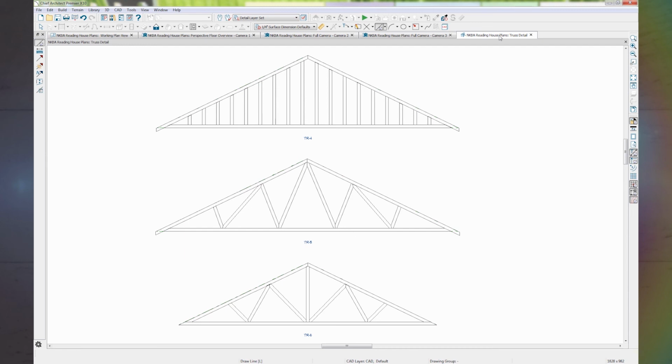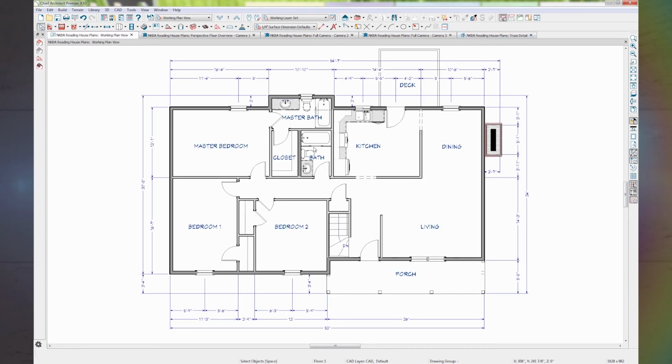Therefore, all of the interior walls on the main level of this home will be non-load bearing. There are some walls in this home that shouldn't be relocated. For example, the wet wall for the hall bathroom.